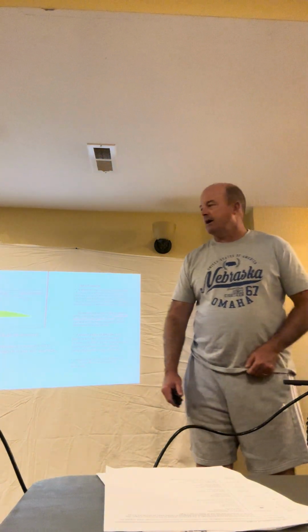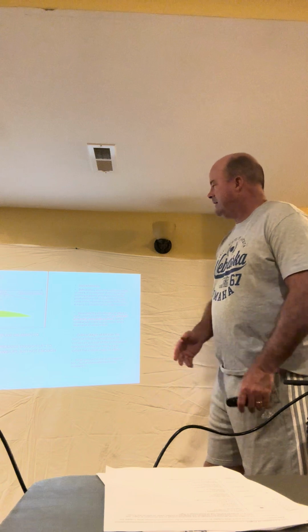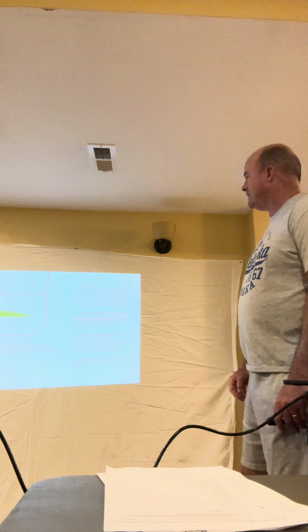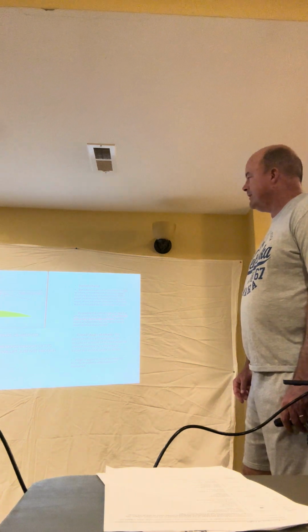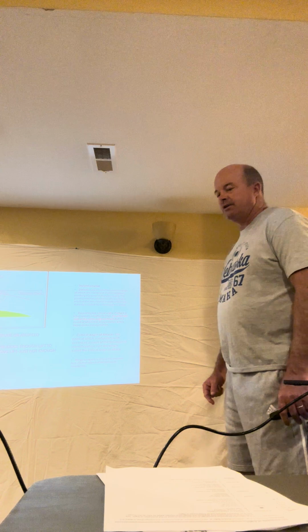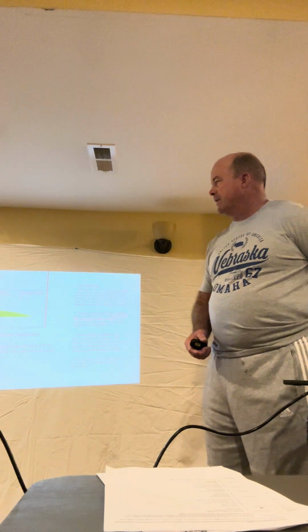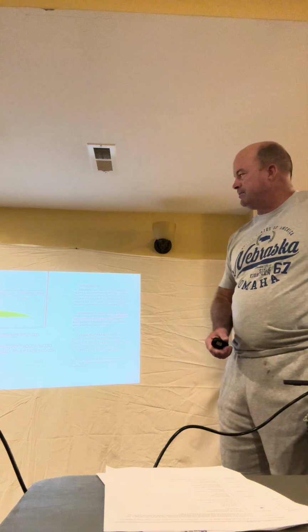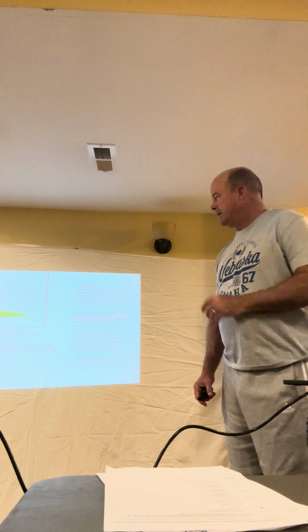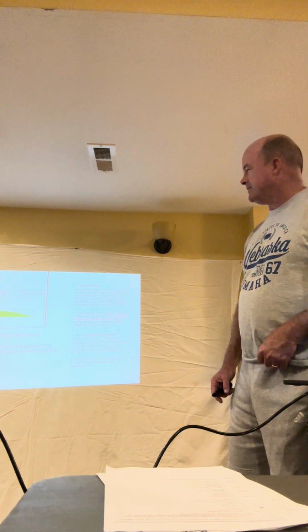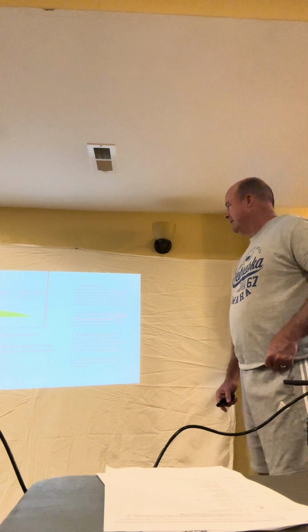All right, so we're going to talk about angle of attack, and we're going to talk about stalls, when an airplane stalls. Most airplanes will stall right at 20 degrees, right? But the big thing to remember is it can occur at any pitch, attitude or airspeed. A stall means the wing is no longer able to produce enough lift to generate flight. It is still producing lift, just not enough to produce level flight, right?